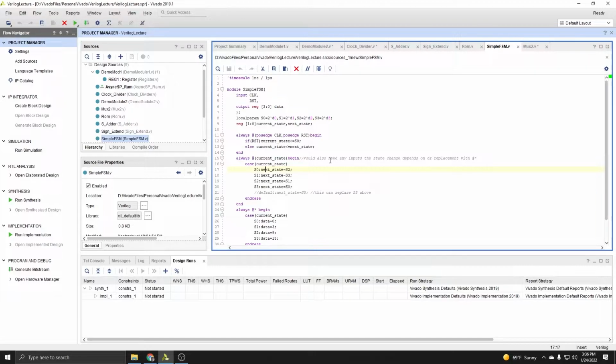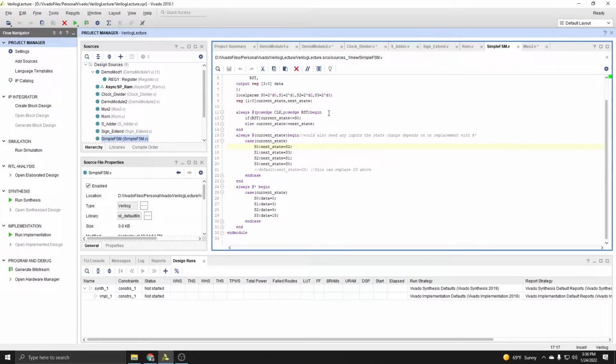And each gate requires the input of the next gate. So what it does is it will force the next instruction in whatever code block you're in to wait for the previous instruction to complete before it continues, so that it can take the result of that into its own. Now, the non-blocking assignment, which is this one, does not do that. All non-blocking assignments within a code block, or within any always block, occur simultaneously, which allows you to simulate sequential logic.